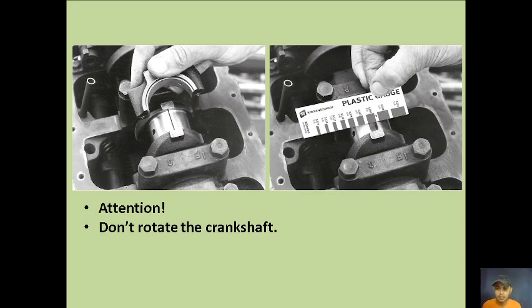Okay, so you can see here we have an inch and a millimeter reading, so you can compare this one. So attention, don't rotate the crankshaft because the plastic gauge will be flatter than what it's supposed to be.